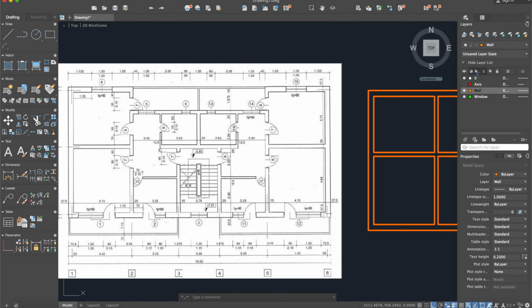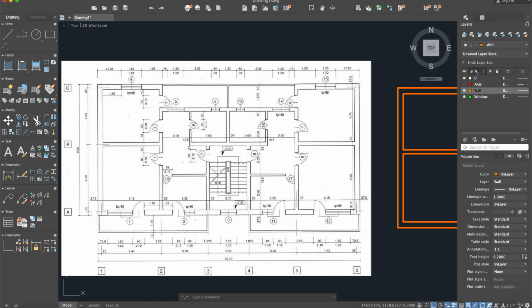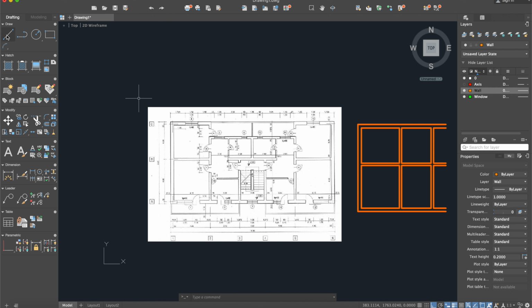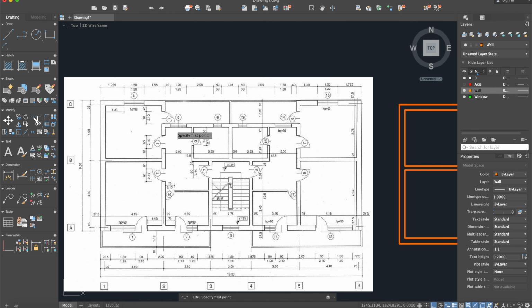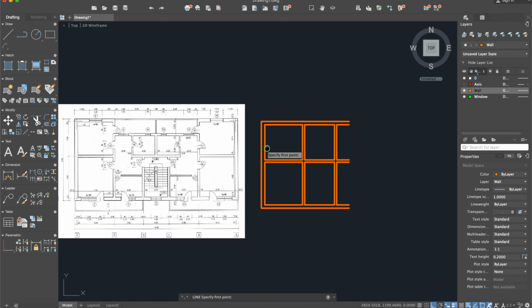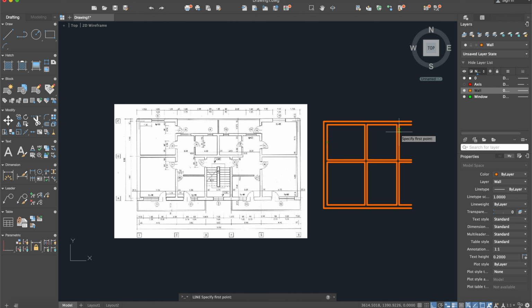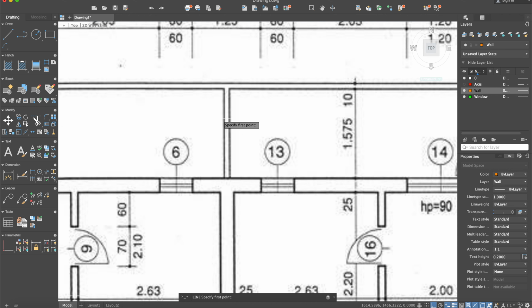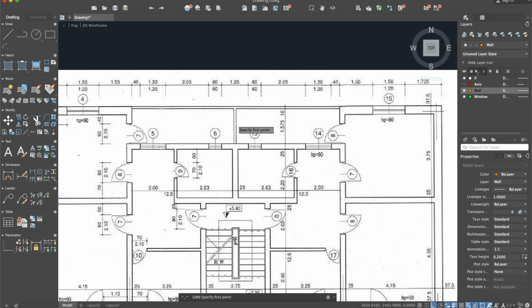The next step is to see where we have an open space, for example, a door, a window, or something like this. But first, let's start to do all the walls. So here in this case, we have a wall that we don't have, so we must construct it. And this wall, we don't have it anymore. But the exterior wall here will be at a distance of 5 from the axis, because this wall is 10, so on each side it will be a distance of 5.